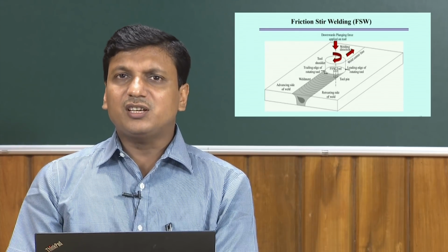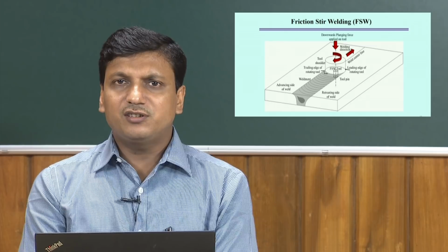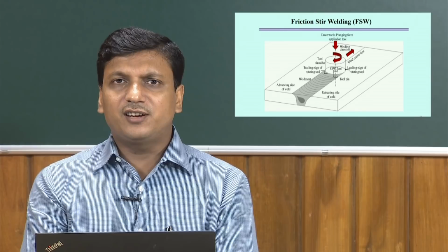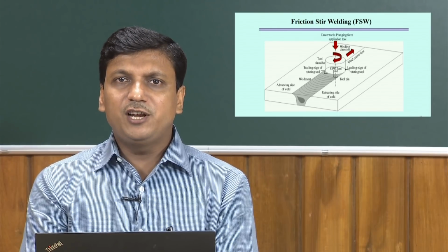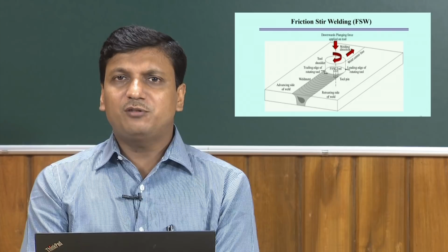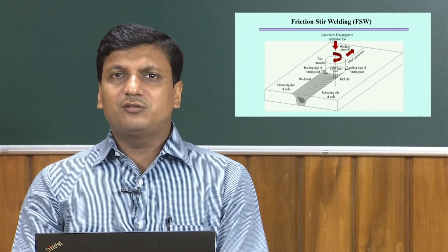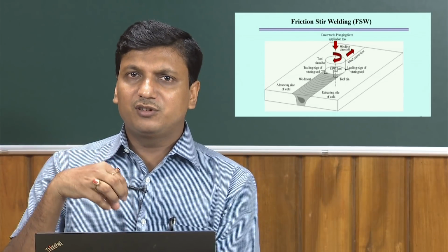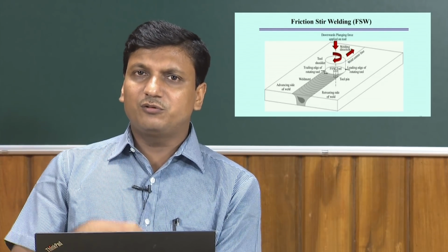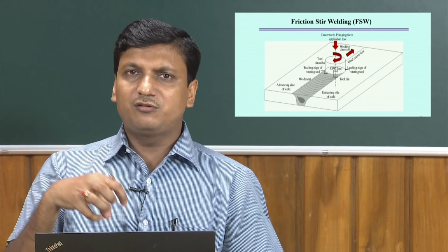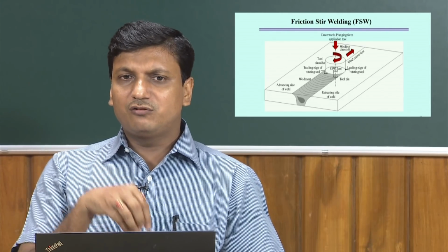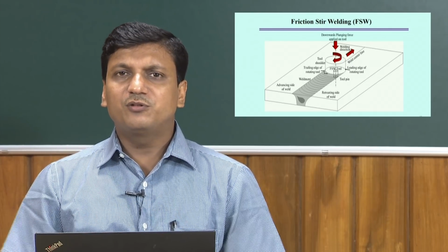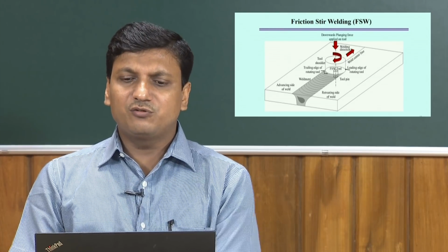This friction stir welding process at the very beginning started by converting the simple milling machine process into the friction stir welding process. In the milling process we use a rotating tool that we hold and rotate, and that tool is inserted in the workpiece, and then the transverse movement of this rotating tool helps to make the solid state joining of these two materials.